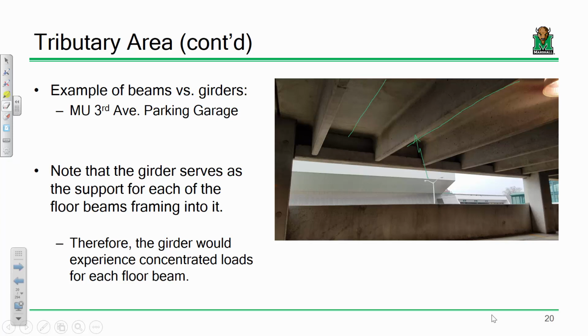Let me ask you a question. Would this at all change if I turn that into the roller and that into the simple support? Would it really be any different? No, right? This has the same moment diagram as the previous problem. Same shear diagram, same deflection, same everything. So much so that these and these in a whole bunch of structural engineering scenarios are sort of treated the same. And we sort of call them simple supports.